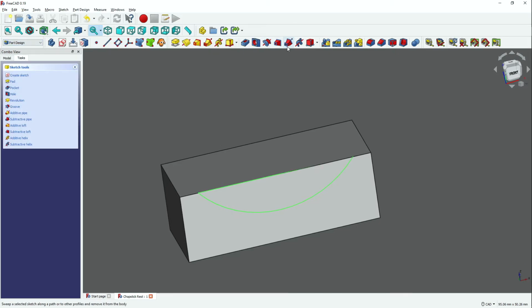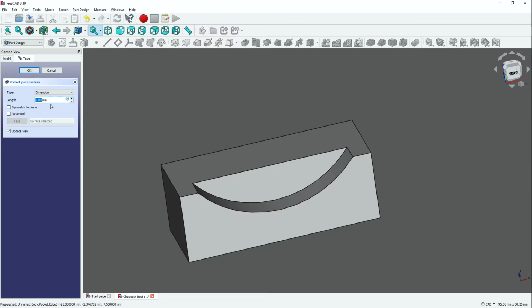I'm going to go back to Part Design. And so it looks like Pad is kind of your extrusions or your extruded boss or whatever that you might not be aware of. These are kind of commands in other softwares. And Pocket is for removing material. So Pad makes material. These blue ones kind of cut things. That kind of makes sense. I mean, even with the fillets and chamfers over here, that's kind of how those work. They remove material using, this one uses arcs, that one uses angles, you know, math. But so Pocket, and it already created here, you can change it.